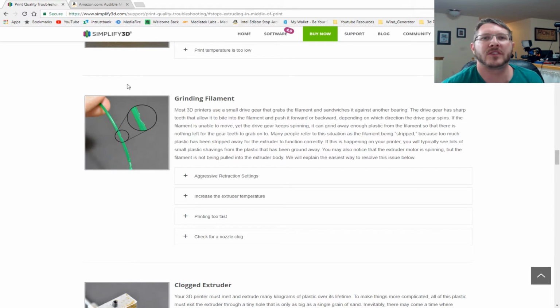In that case, I would suggest taking off the print head, the little unscrewable part, the extrusion head. Unscrew that. What I've done in the past, believe it or not, is run a little drill bit through it, like a little 4mm drill bit. You can find those on eBay, they're not too expensive. If that won't work, another method that I've used, and it actually works fairly well, is if you have a propane torch, put the head in the propane torch and let it heat really hot, and the plastic should drip out of it.